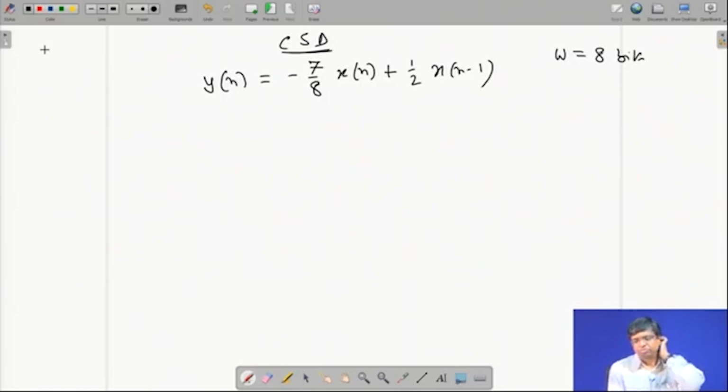That will be a bit serial FIR filter. But remember, this basic equation cannot be violated. This is the actual digital filter. So whatever we do inside, bit serially, all those manipulations, this basic equation has to be satisfied. I should generate the same yn which the bit parallel, ordinary FIR filter was generating. Fine.